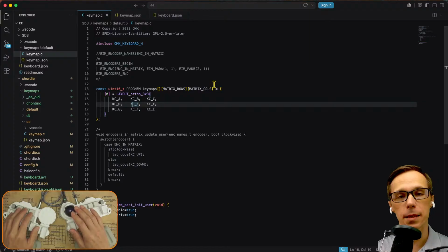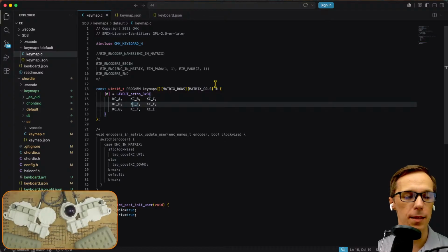I mean, we were getting some readouts on the oscilloscope. They didn't look quite okay, they looked kind of weird, but now I know that they were okay. The reason we were getting such a weird output from the keyboard was that it was trying to interpret all those inputs as an encoder input.